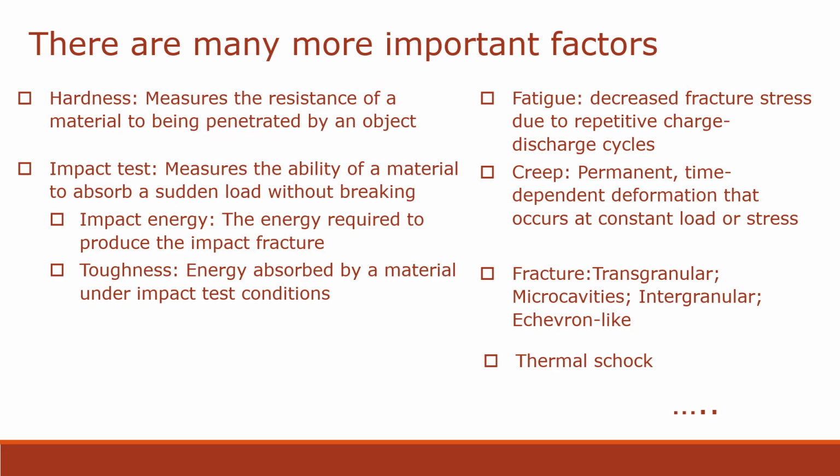Then creep is the permanent time-dependent deformation that occurs when you apply a constant load or constant stress. Typically, it's very slow, but over long times it can have some problems. It's very typical when you see, for instance, pipes. It's quite easy to see. In pipes or in cables, too. Then fracture: microcavities, transgranular, intergranular, through microcavities, and chevron-like.